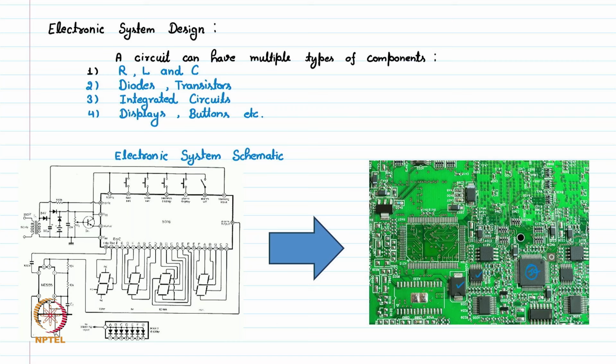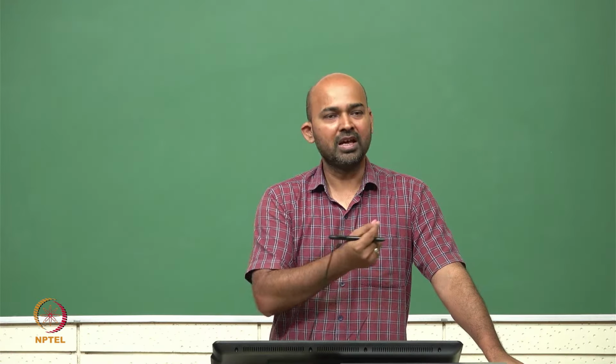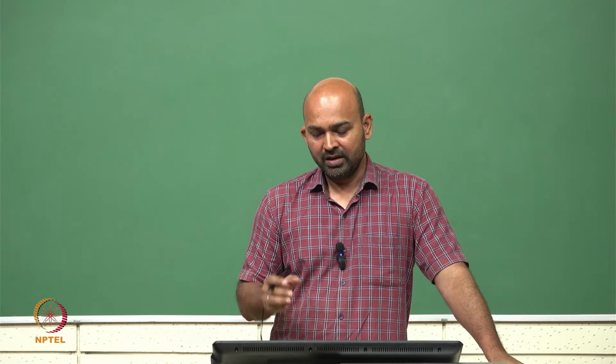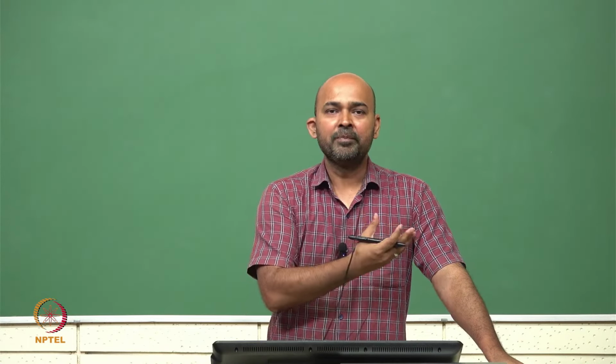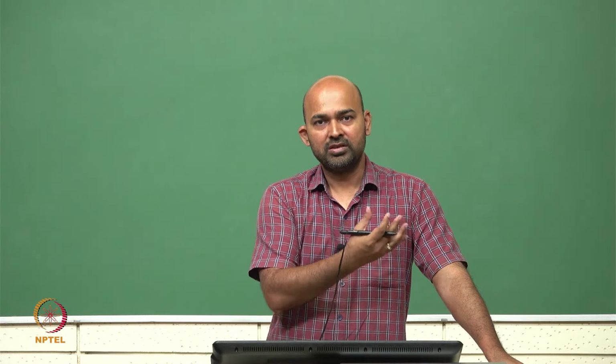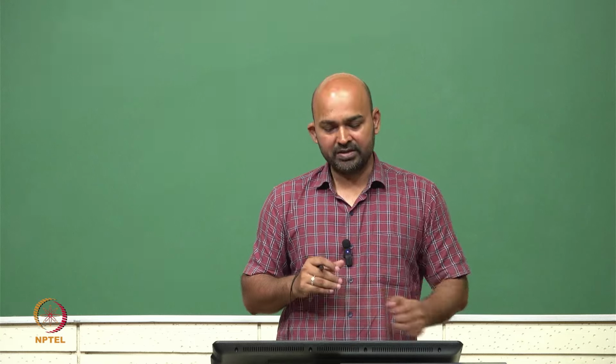It means inside this there are multiple semiconductor based devices. For example, there are so many transistors inside these ICs, and we may also need some discrete transistors as well. A transistor is available in discrete form where only one switch is available, which we can buy and put on the PCB. So these semiconductor devices come in two forms. One is the discrete form, where only one device is there, just like one resistance, it is one transistor. And we may have integrated circuits, where so many transistors are already joined together to perform a certain function.